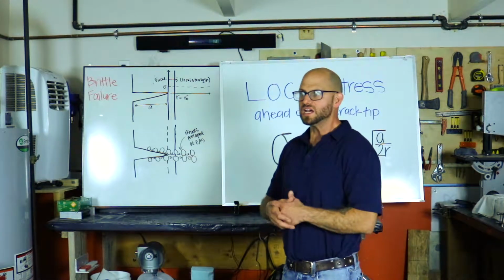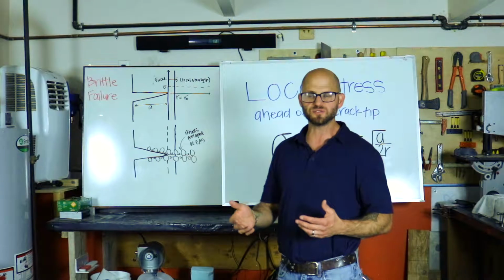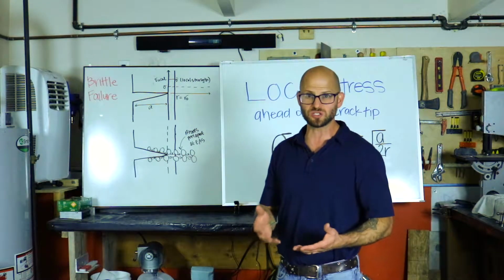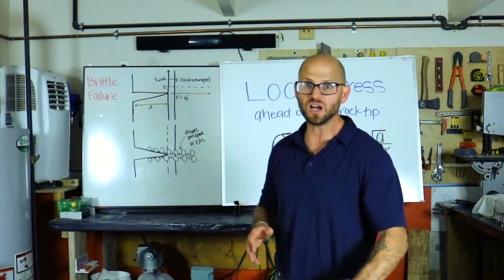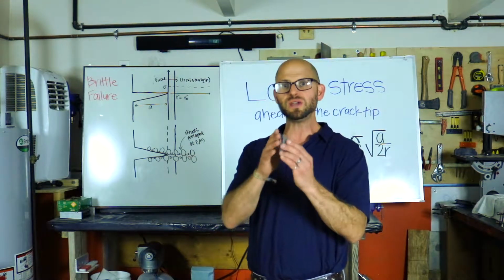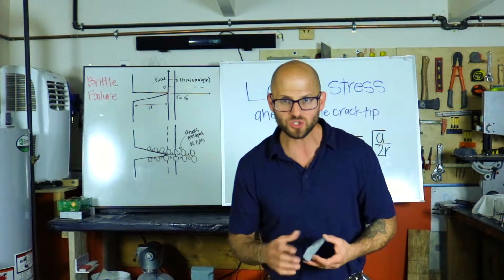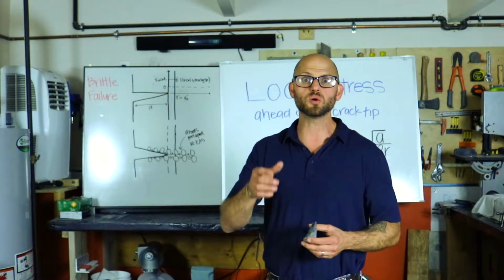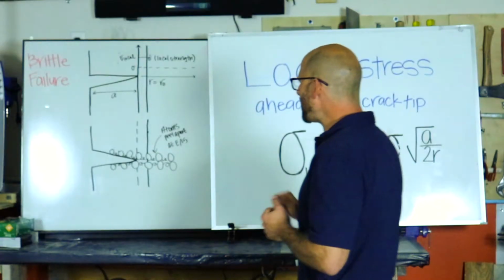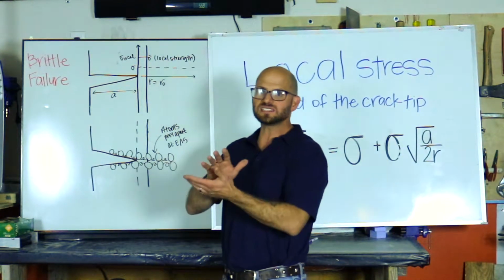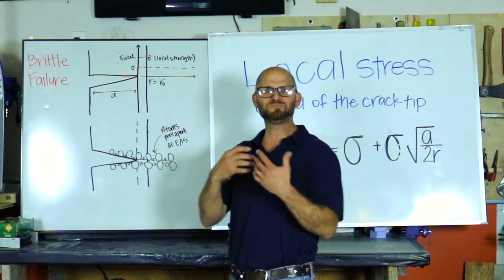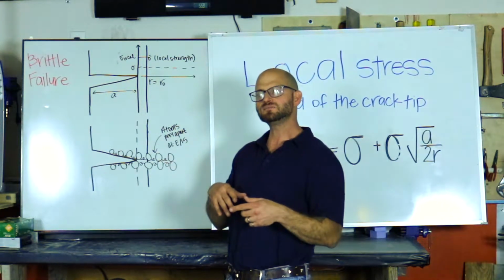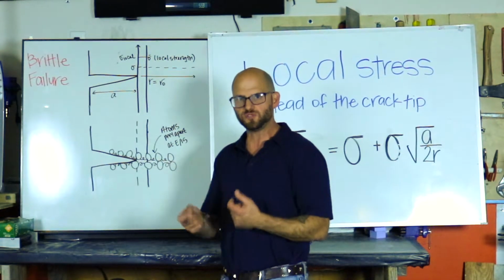We know this, that in many different books and a lot of different research, concrete is talked about excessively, that it can't handle flexural, tensile, or shear stresses very well. But more importantly, when we see concrete fail, that hydrated cement matrix, especially the higher strength concretes or grouts, goes through a certain type of cleavage or brittle type failure. And when we look at it, we see this cleaved or brittle type failure has a very smooth surface compared to a more ductile failure that has a rougher surface.